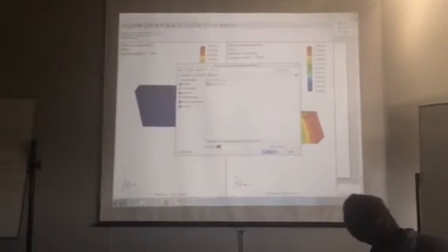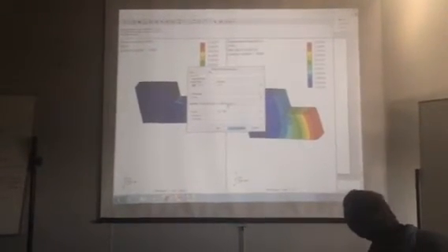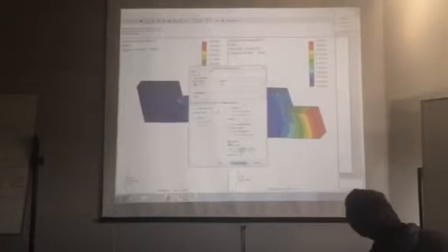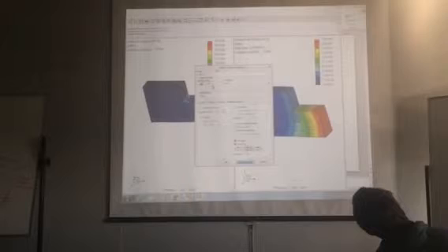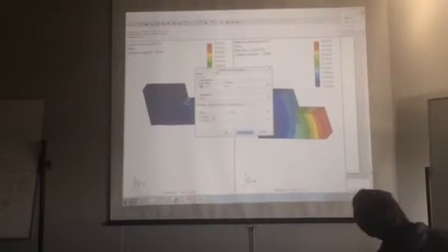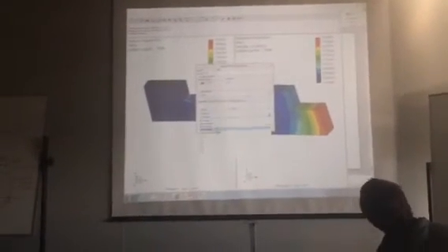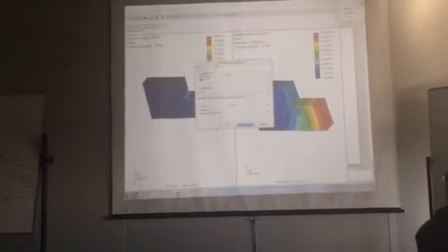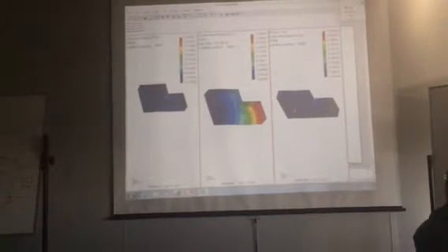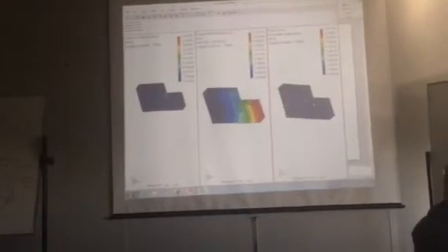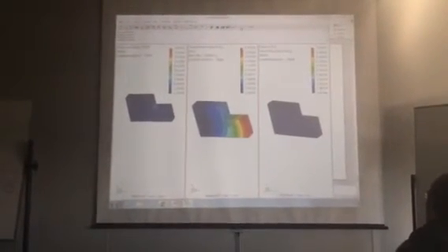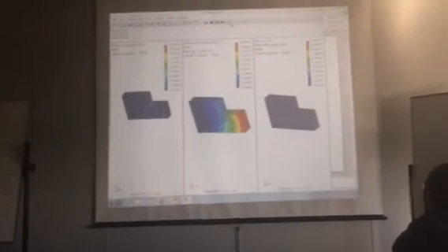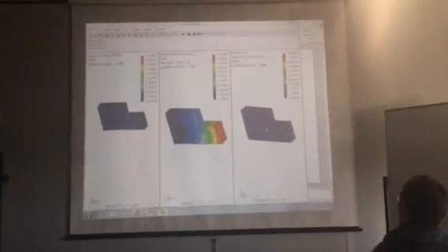you can, we'll put another one in, and this time we'll put an animation in. So what we're going to do is, instead of von Mises, we'll do maximum shear stress, and we'll go OK and show. And this time I'm doing an animation, so it's showing here. I can control the speed and so on of that animation. Slowly. So you can see the stress building up.